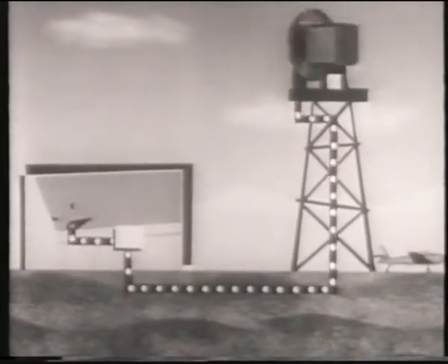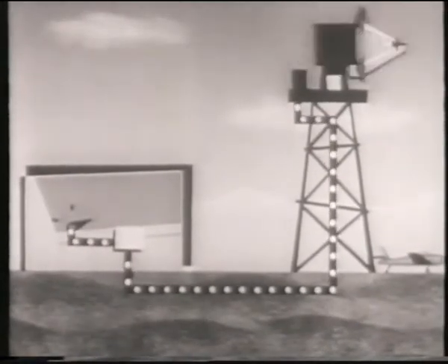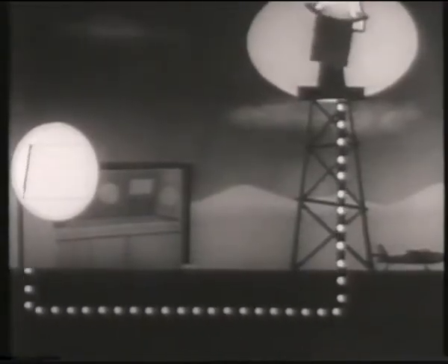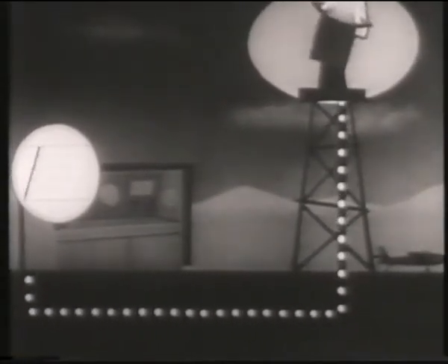The beam of radio energy put out by the radar antenna is narrow and highly concentrated and can be rotated or directed as needed. For example, a vertical beam can be rotated through 360 degrees of azimuth, or it can be moved from side to side. A horizontal beam can be moved up and down to provide return indications about the height of objects.